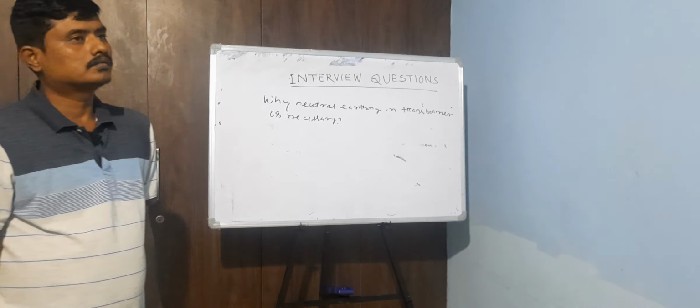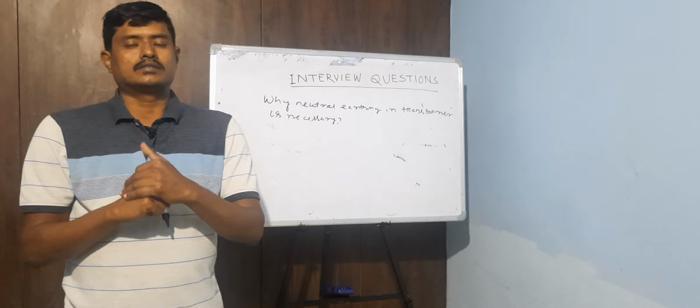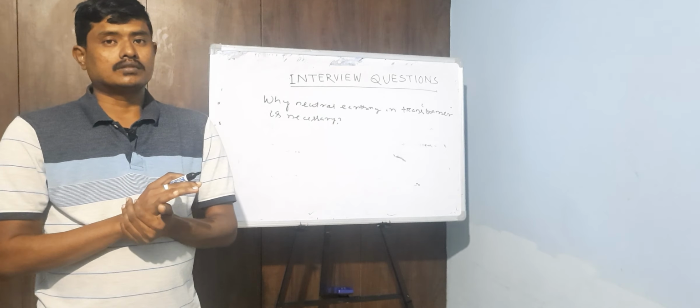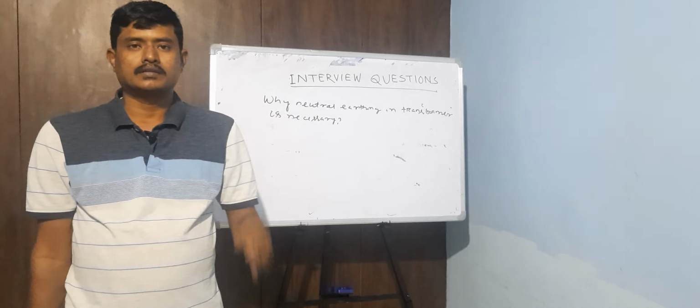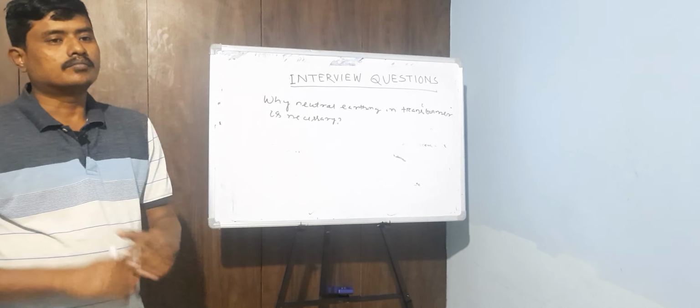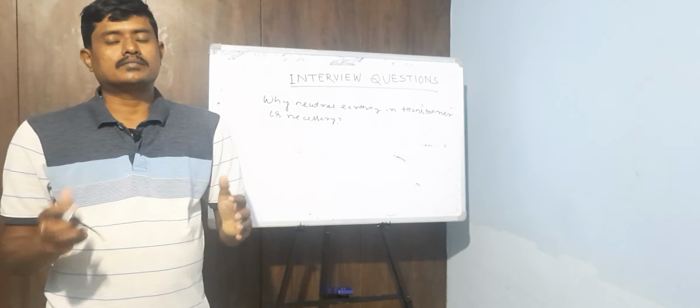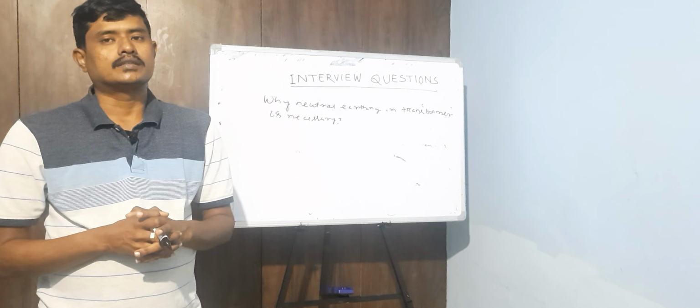Because due to neutral earthing, it stabilizes the high fault current and it maintains balanced voltage in the secondary side.